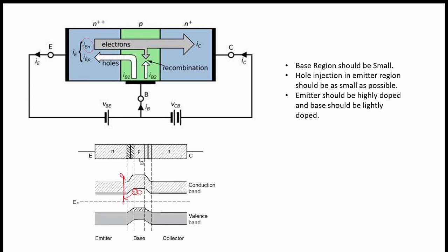We are decreasing the depletion region width and the potential barrier, for the electrons as well as for the holes, so both currents will flow. Electrons flow from the N region to the P region, and holes flow from the P region to the N region, but the direction of the current will be the same, because if the electrons are flowing in this direction, the current will be in the opposite direction.